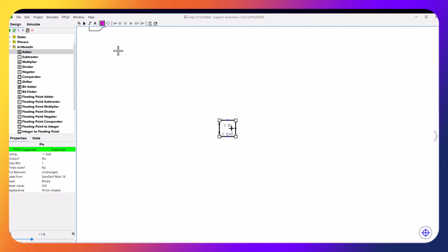Let's just do some demonstration. So I'm gonna do the same thing I did before. I'm going to connect the input to the first input, and you will see that they have an orange line that says there is some compatibility problem. Why? Because the adder expects 8 and the input is 1. So you can change either one to make them compatible. So I'm going to change this guy and make it 8.